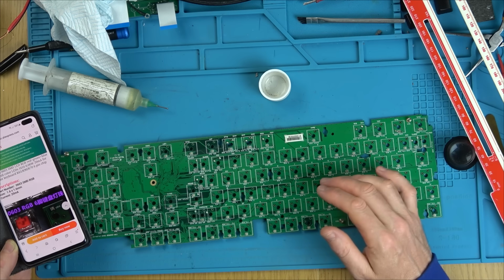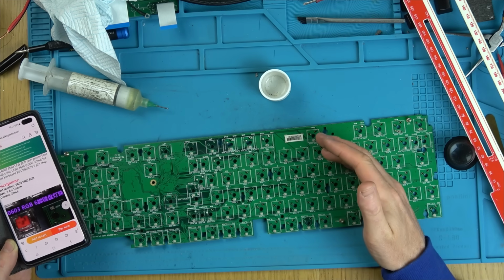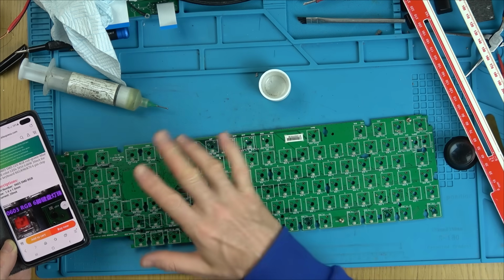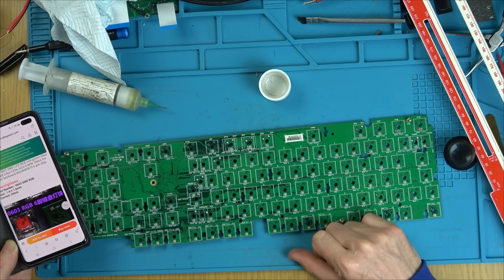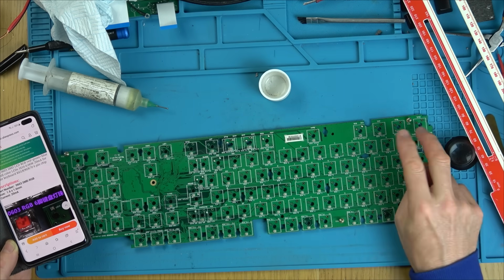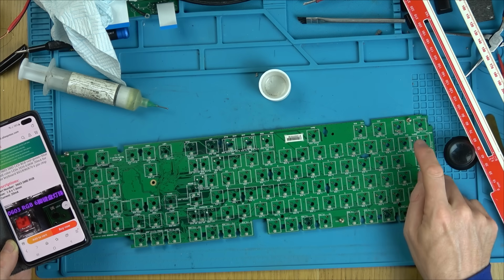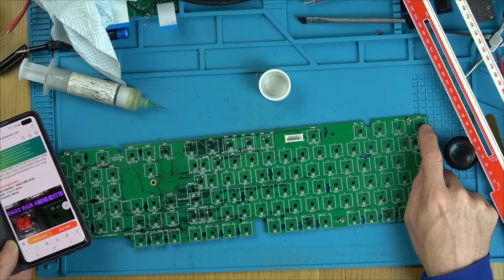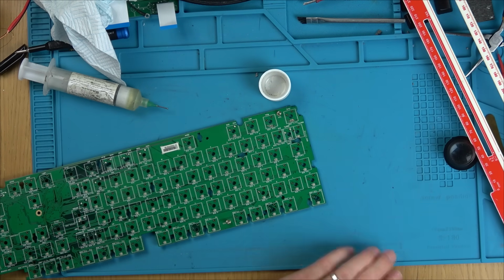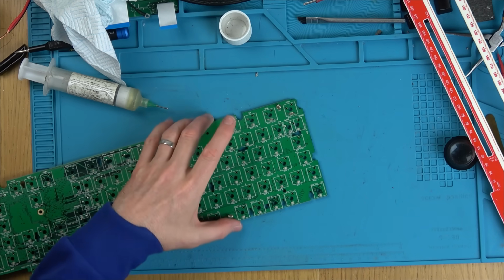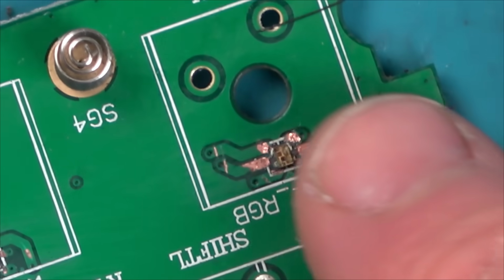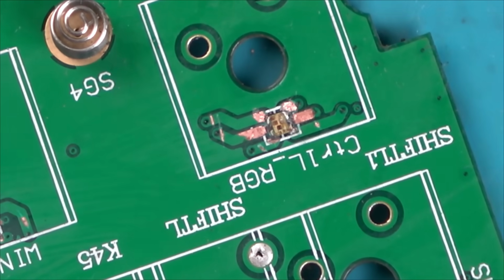No sane person would be doing this because what's the point? You've already got your lights on your RGB. It's only if you wanted pure yellow or pure blue you're going to notice them. If you have some cascading effect, realistically you're not going to notice them. But as I say, I've come this far now, so I might as well go a bit further and see if we can get some new LEDs on and then see if it starts working. I might get to the stage where when I take them off there might be complete corrosion underneath. In fact, I'll tell you what we'll do. Before I buy them, let's take off one of these just to see how corroded the pads are, because maybe the pads are completely eaten through. If they're nice and clean on this one here, there's a good chance it's going to be okay on the rest of them.